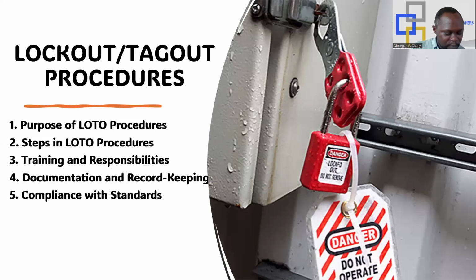Okay, you also perform your own LOTO and take your own keys. Yes, you use your own LOTO, and take your own keys. Your life is in your hand. So it's either you drop the key or you take it along with you, but it is advisable that you go with your key.